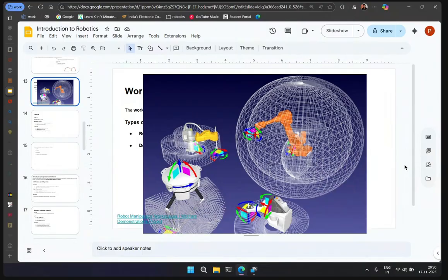Now when I apply more weight than desired, it is made for like a 100 to 200 gram payload. But if I put 2 kgs, even 1 kg, the whole robot, which should be perpendicular at 90 degrees, bends around 30 to 40 degrees, because I'm using plastic parts.